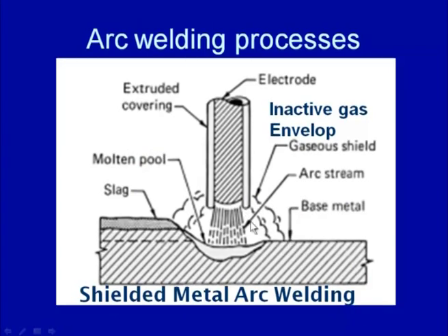But this kind of shielding is not found to be very effective, because the gases generated form the cover on their own, and there is no specific driving force to form a complete cover or shielding all around the weld pool, and that is why there is always some possibility for atmospheric gases to be present in the weld pool.